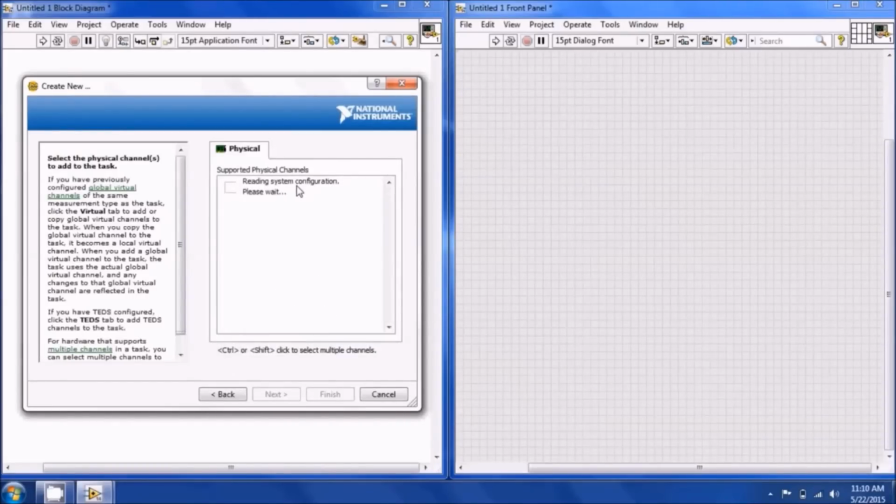And once you select what type of signal you want to acquire, now this is where you select your DAQ. So the DAQ I have connected is an NI 9215 BNC DAQ. You're going to select the channels. You see the channels for that DAQ. You see all 4 channels there. And if you remember from the DAQ video, these are the AI0, AI1, AI2, AI3 channels, which correspond to the 0, 1, 2, and 3 below the ports on the actual DAQ.